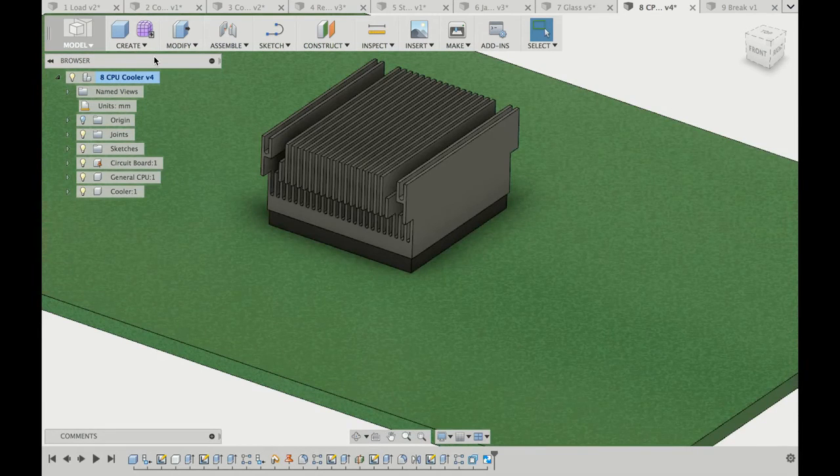The heat transfer values you put in are for flat plate heat transfer, like the overall heat transfer values, because the geometry is being taken into account. These were taken from the tables just for this demonstration. So it could be more complex to find out for various types of materials and geometries. There are some empirical rules for how to select it, but in this case I just selected this one to demonstrate it. So how do we figure out the right U value, because picking it is key to getting the heat transfer calculation right?